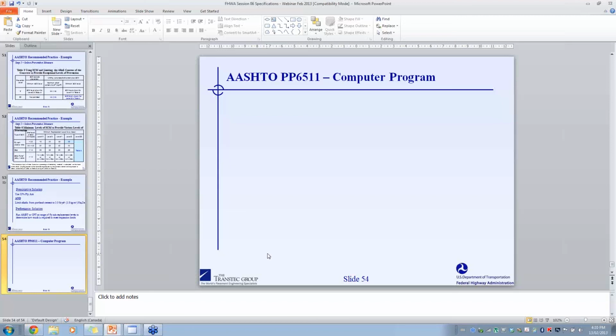If the plot of your chemical analysis for the limestone aggregate that you have actually falls into that section, the aggregate can be considered as potentially alkali carbonate reactive. If the chemistry is such that the composition falls outside of that zone, then the material will not be considered as potentially alkali carbonate reactive, and then you can subject the material to the 1260 accelerated mortar bar test or concrete prism test.